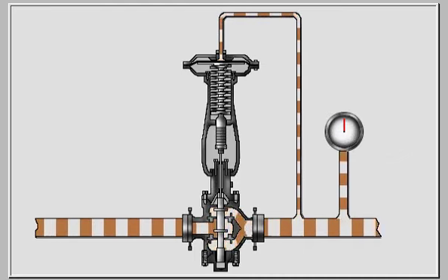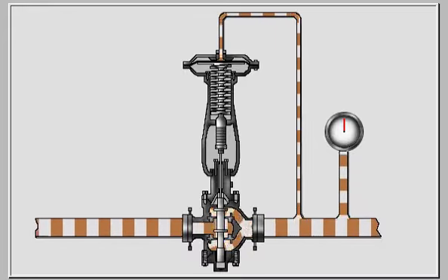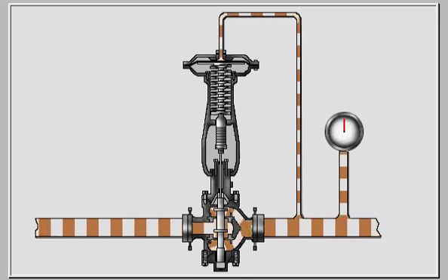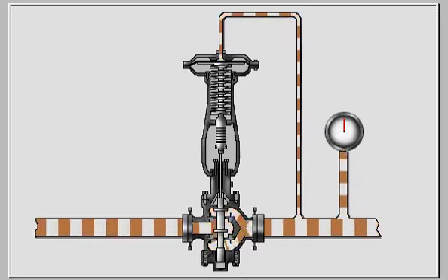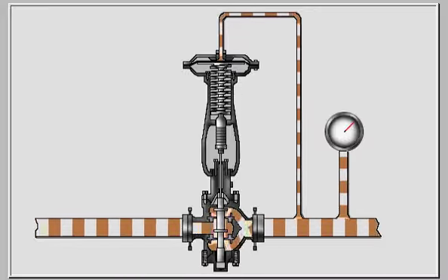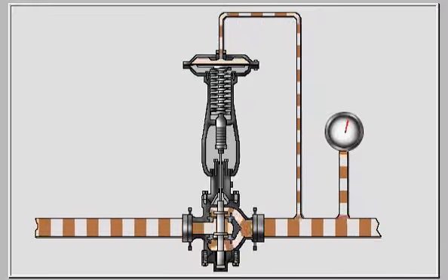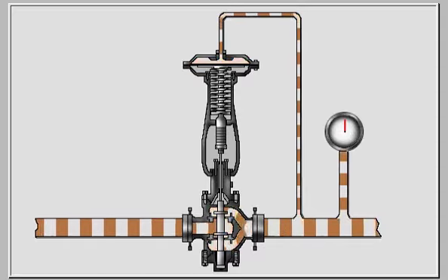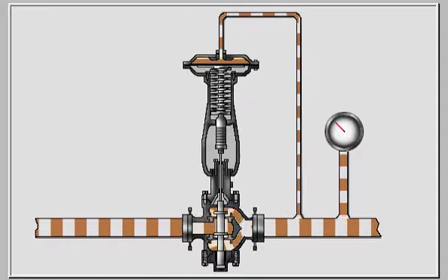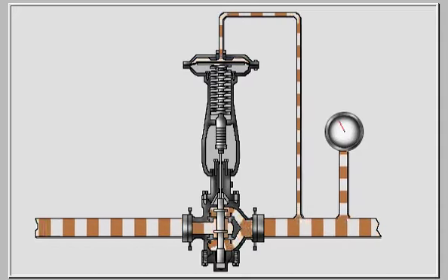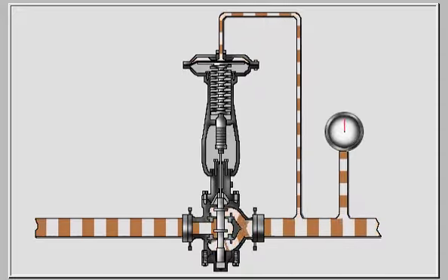The top side of the diaphragm inside VPR2-1 is connected to the bearing header downstream of the regulator valve. The bottom side of the diaphragm is connected to the actuator spring. If lube oil pressure in the bearing header should increase, the diaphragm will be forced downward, lowering the valve plug until the bearing header pressure is reduced to 26 psi. If lube oil pressure in the bearing header should decrease, the diaphragm will be forced upward by the actuator spring, raising the valve plug until the bearing header pressure is restored to 26 psi.